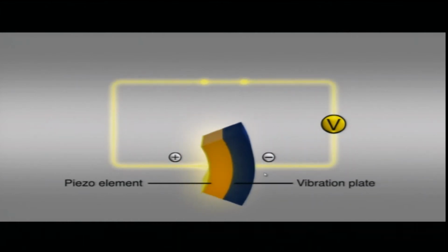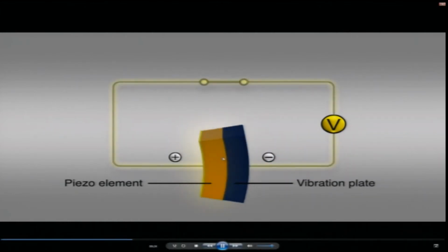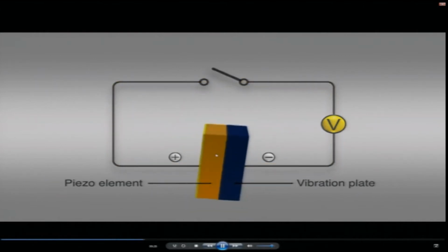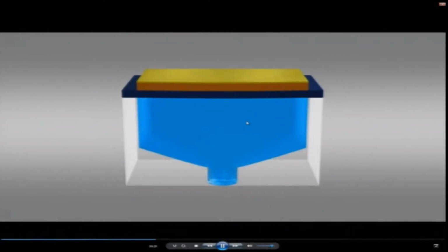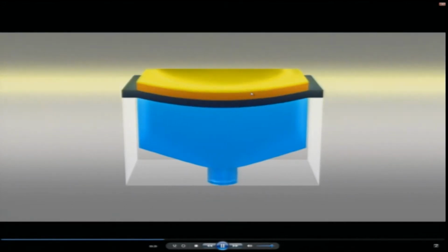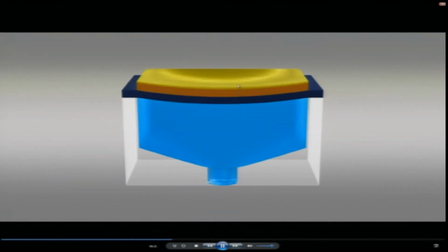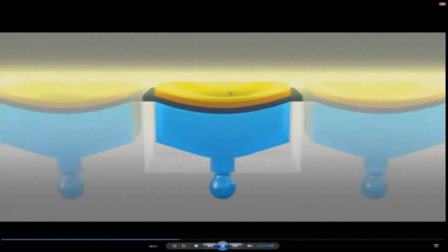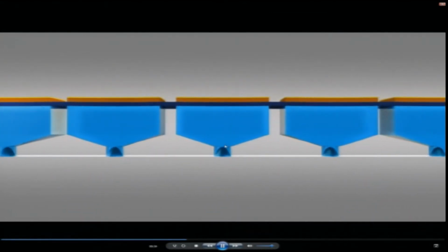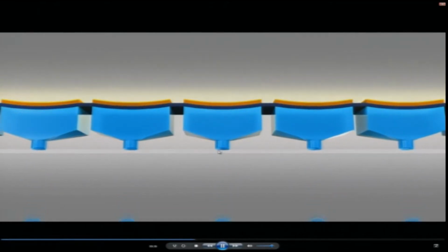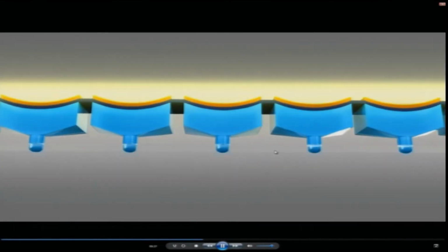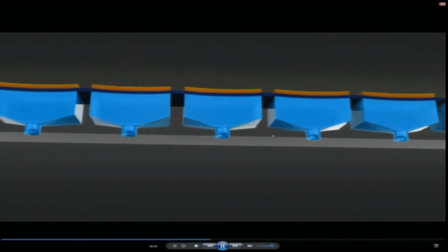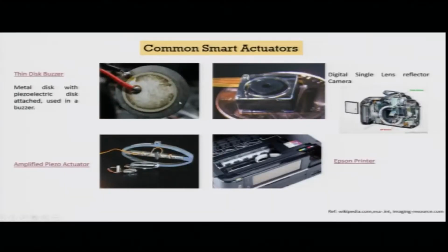Okay. So, if you have two layers like a unimorph, where one is active and one is passive, then you can get even bending in the system. That is what you look for. If there is a bending, then that will push the ink, and you see the ink coming out, and many of these together form the printing pattern. So, you know now how you can develop such actuators using smart materials. This just gives us a glimpse of the whole thing.